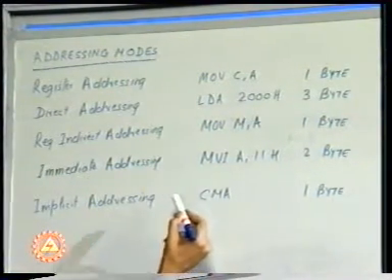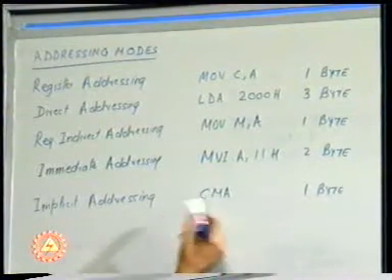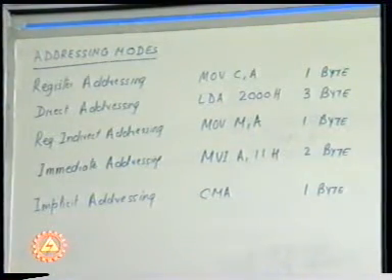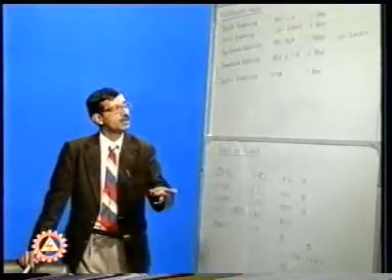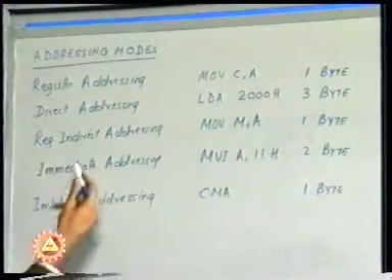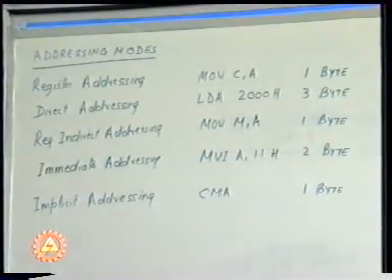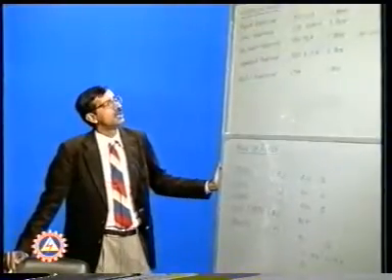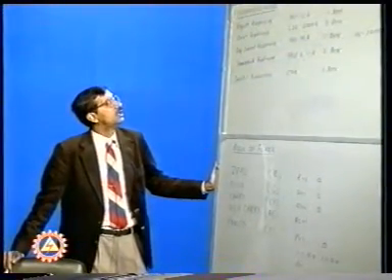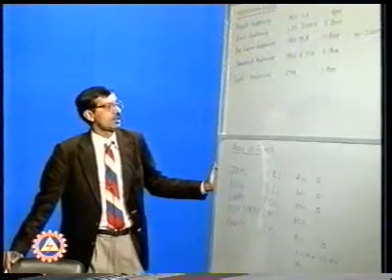We have not specified any memory location. We have not specified anything beyond this except the instruction itself, which automatically will find out the location or the address where the action is to be carried out. This requires 1 byte. So looking at these different addressing modes, one can have some idea regarding the number of bytes required for implementing the instruction.